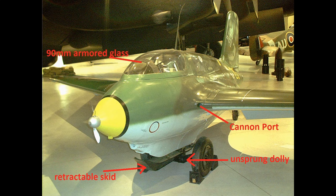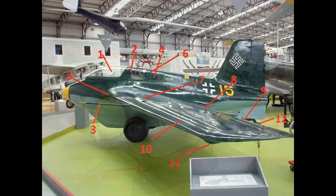This could happen not only due to mechanical failure, but from the pilot failing to return the skid control lever to neutral after extension. Moving to the side, at position 1 we have the canopy. It's hinged on the right side and it can be jettisoned. However, at least one report says that the air pressure around the canopy could prevent it from departing the plane while in flight at certain speeds. In other words, you could jettison it, but it would just more or less stay in place.